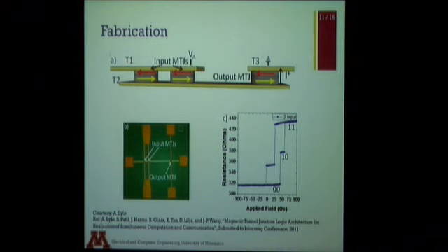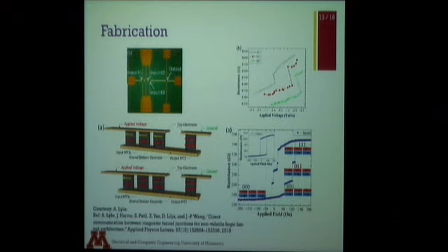They also did something very interesting with this. They also fabricated 3 input MTJs. Again, that looked exactly like the 2 input MTJs. There were now 4 pillars of MTJ stacks on this one shared bottom electrode, and that was the graph that they got out of it.